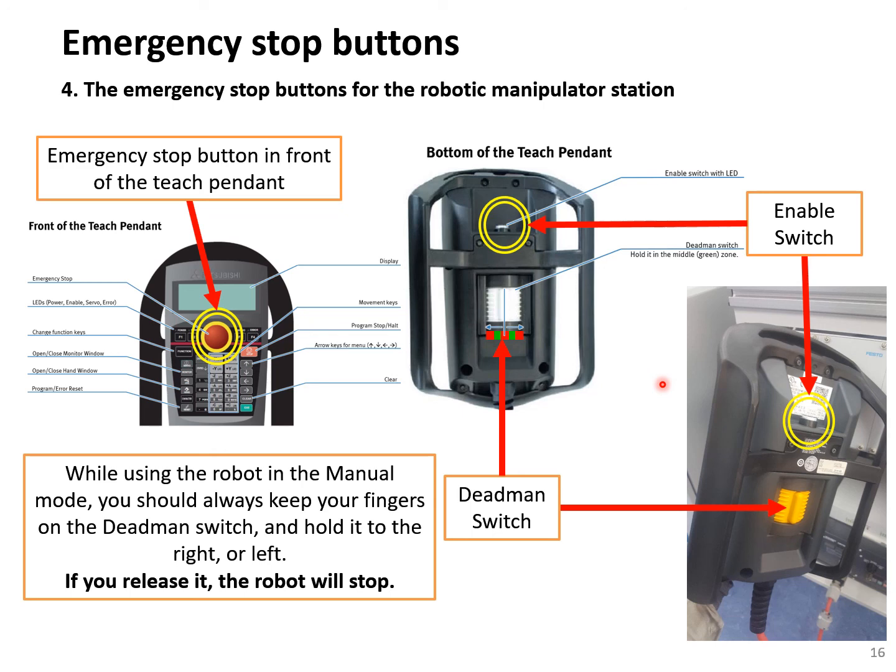So for any reason, for example, if one sensor breaks and the robot could go crazy, operators should be able to stop it immediately. That's why these teach pendants are equipped with alternative methods of stopping the robot. Okay. For example, for this one, we have a dead man switch. Many of the teach pendants are equipped with the dead man switch. I will explain what this is when it comes to the robot, or this enable switch. So these are alternative methods to stop the robot.